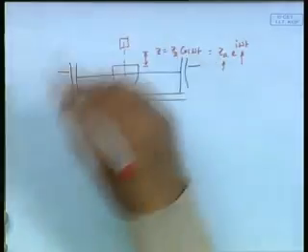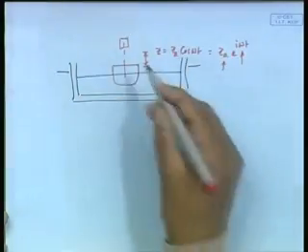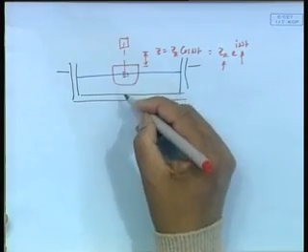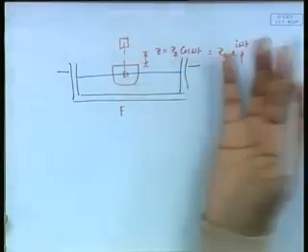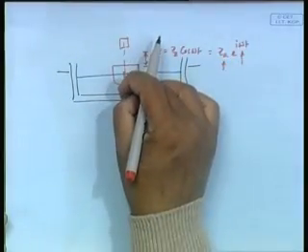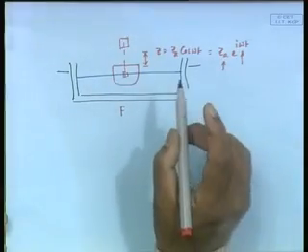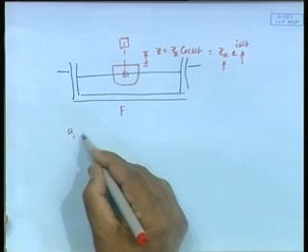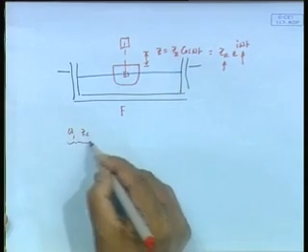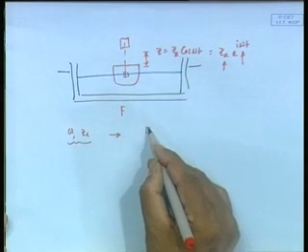I can have a mechanism, some kind of circular mechanism by which I push it down. Then what I do, by an instrument here, I measure the force that is been required to push it down, the force that is coming. Okay. So, what I do is that, remember this force oscillation test, for a given known frequency omega and for an oscillation amplitude A, which should be sinusoidal, I am measuring Fz.